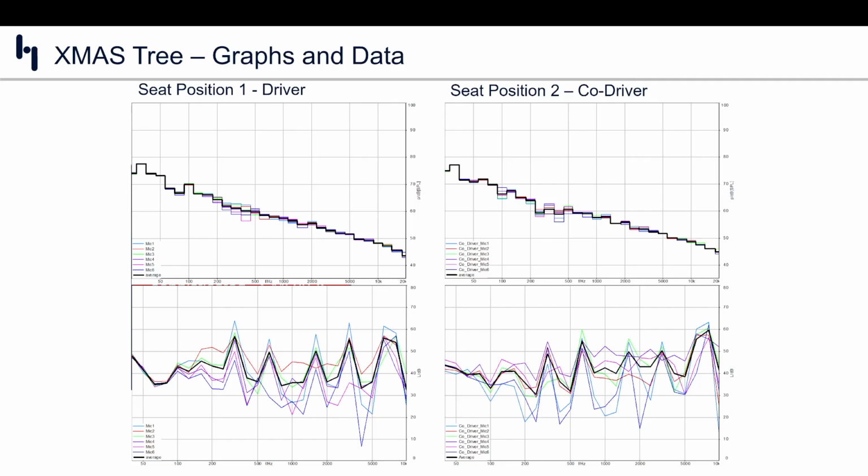For distortion measurements, we can resort to the good old total harmonic distortion or THD plus noise measurements, as they are as fundamental to audio engineers as frequency response measurements. We'll want to capture the distortion artifacts for all frequencies, so if the system permits, we can apply a stepped sine or a Farina sweep to document the distortion of the audio playback system.